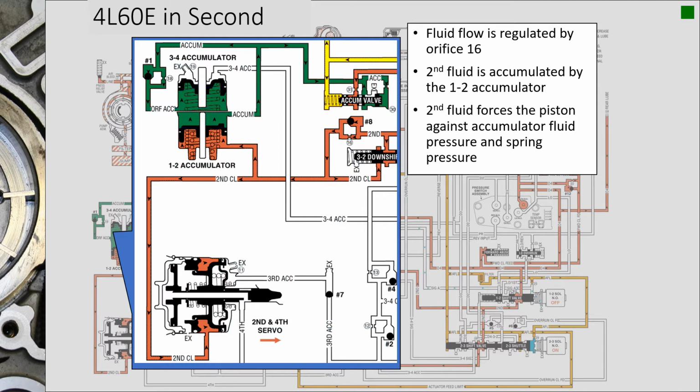And they're not. The spacer plate that separates the valve body from the case is actually right between there. Yeah, there is green fluid and it's the same pressure, but they are separate. These two circuits are separated from each other by gaskets and a spacer plate that divides it right down the middle. It just doesn't do a very good job of showing that.